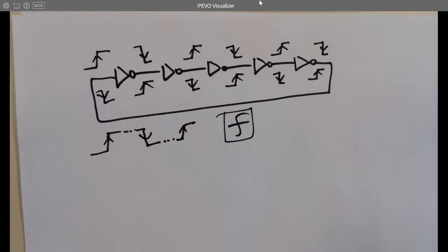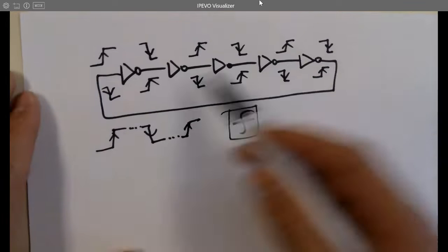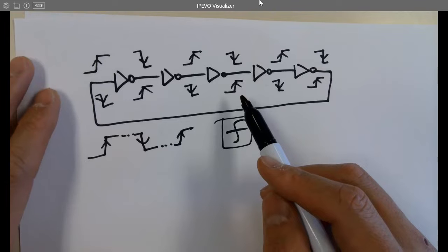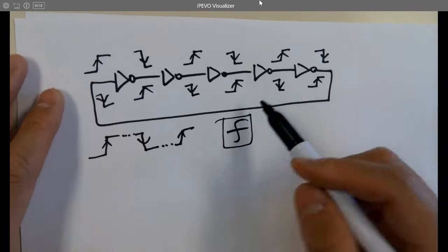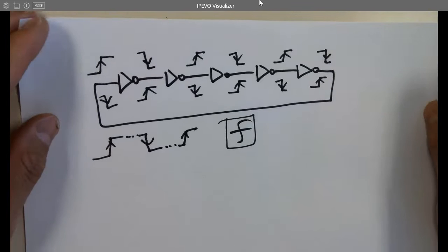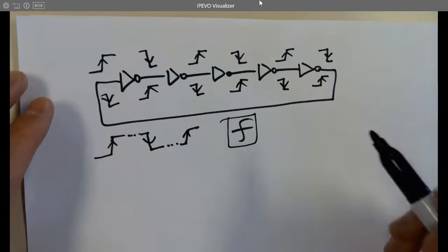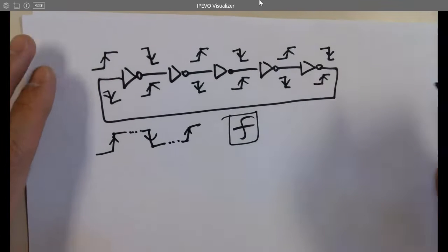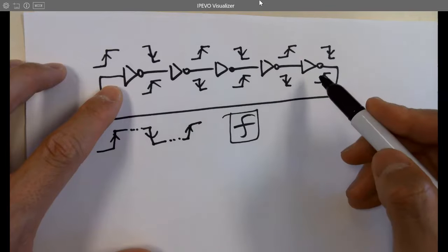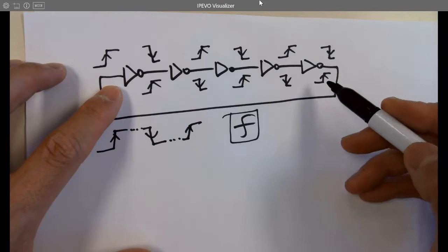2 megahertz, for example. But sometimes you need to divide the frequency of the original clock on the board to a frequency that you need for a certain part of the circuit. And you can have an internal ring oscillator. Also these can generate a super high frequency, in the range of a few gigahertz. I think a couple of years ago when I was reading some papers, they used the ring oscillator because it can generate a super fast clock as a shutter for a high-speed camera.